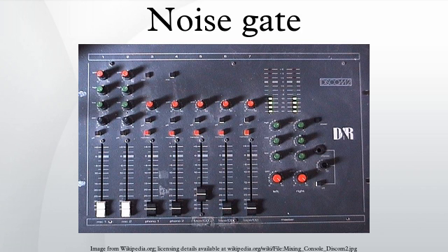Noise gating works well when the static is steady and either narrowly confined in frequency or well below the main signal level. In cases where the signal merges with the background static or is weak compared to the noise, gating can add artifacts that are more distracting than the original static.